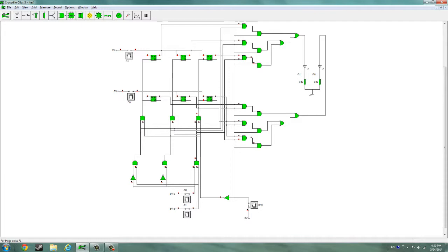So, let's combine all the information about the switches so we understand how to operate the circuit. First, we must set the correct address leads so that the data saves to the correct location. Then, we set up the data that we wish to save. Finally, we set the circuit to write mode, and the number is now saved into the indicated memory cell.